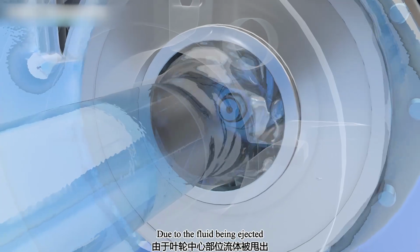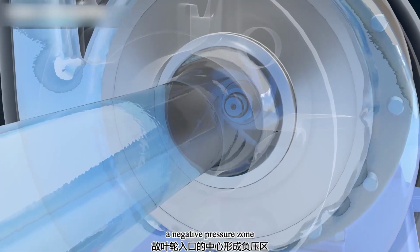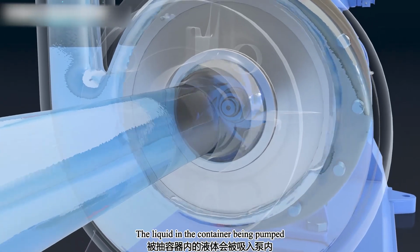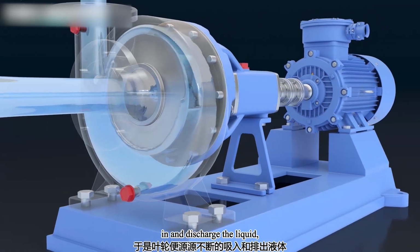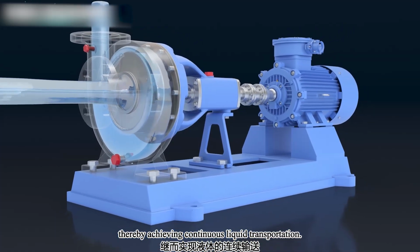Due to the fluid being ejected from the center of the impeller, a negative pressure zone is formed at the center of the impeller inlet. The liquid in the container being pumped will be sucked into the pump, and the impeller will continuously suck in and discharge the liquid, thereby achieving continuous liquid transportation.